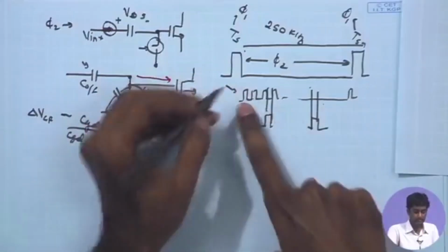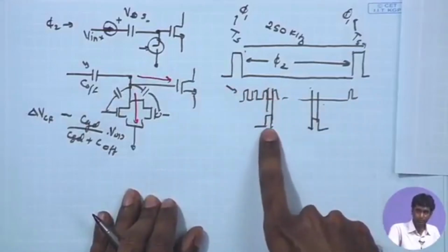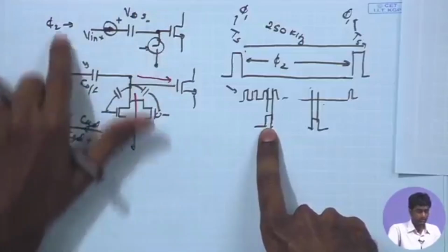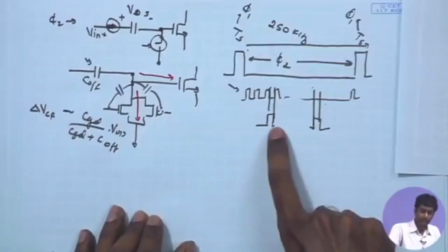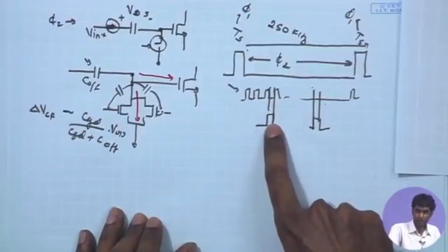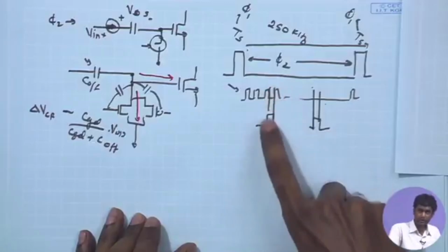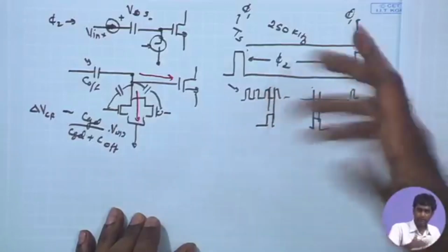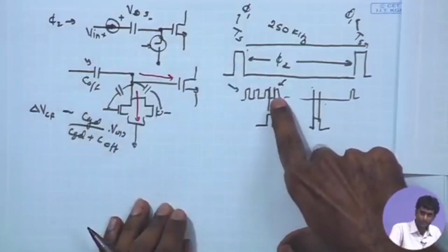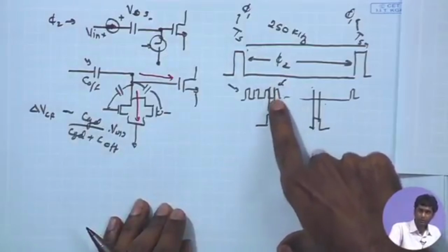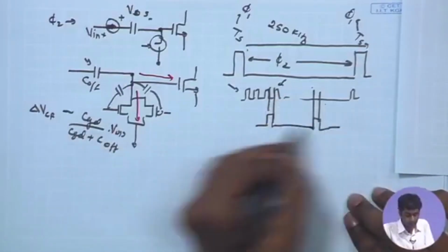So, possibly when this clock for the counter is going down in one of these phases, we can use the offset sampling operation and turn the phi 2 switches off, turn the phi 1 switches on, and again from the next rising edge of the clock we can turn it off. Then we will have to make sure that the comparator output is only being used, say, either in this positive phase of the clock or the downgoing edge of the clock.